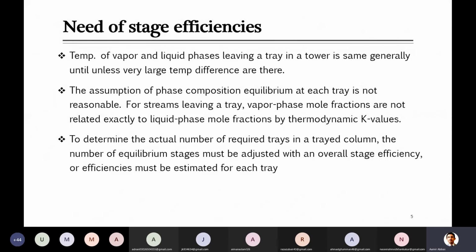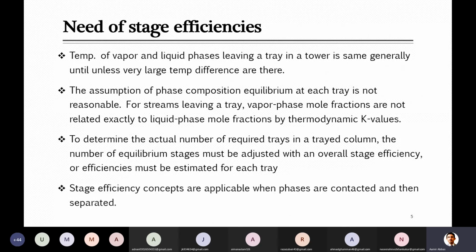the separation which we were expecting, for example, on 5 trays. But as I told you, when vapor and liquid came in contact on the surface of those 5 trays and you don't achieve the separation you were expecting, then in order to achieve the required separation, we need some more plates. Because when we design any column, we want to achieve some separation, and unless that separation is achieved, we definitely have to repeat the process. So to avoid that, when designing the column, you have to consider this factor: in how many trays you can achieve the required separation.